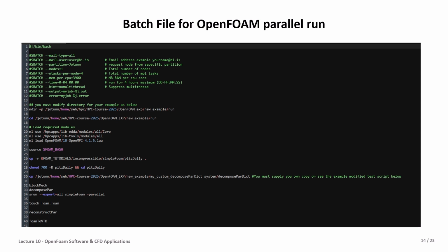To run the simulation, firstly, we need to do the meshing. Then the next command is block mesh. Then the decompose part, which makes the decomposition in parallel from this simulation. So as we discussed in the previous slide when we presented the decomposition type or method in the OpenFoam, we had simple, scotch, and hierarchical.